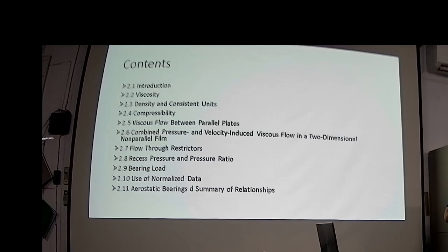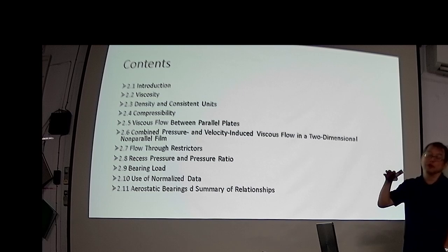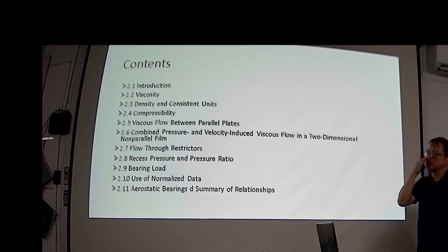So our applied pressure will push the lubricant to move between the two bearing surfaces. That is the pressure-induced flow. And for the slide table, you will have a movement, the moving speed provided by the servo motor. So it is an extra effect from the velocity-induced flow.